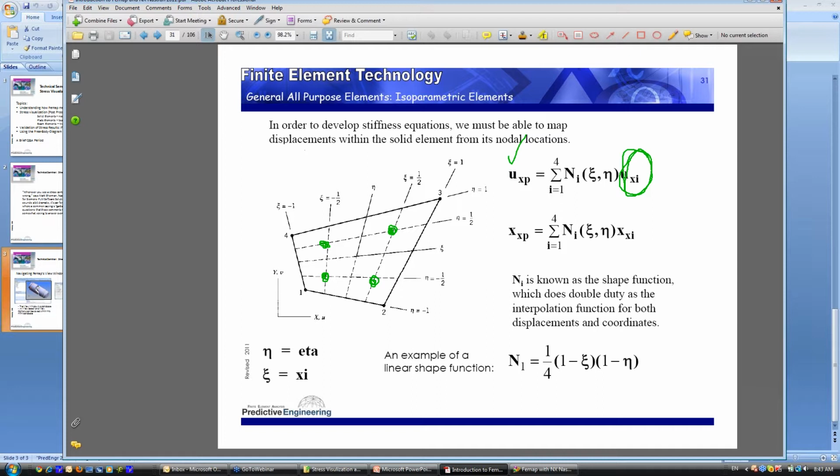So isoparametric elements, you're using your shape function all the way. You're using your shape function to calculate the Jacobian, you're using it to calculate the Gauss points and also to calculate the area or the volume, and then it's used to calculate the stiffness terms, and then it goes back out, calculates your displacements here, and then it goes back in and uses it once more to calculate your strains and your stresses. So your quality of your elements, the closer they are to 1 by 1 for a plate, closer to 1 by 1 by 1 for a TET, the whole process benefits. You get better area, better volume. You get better stresses because it goes back and forth.